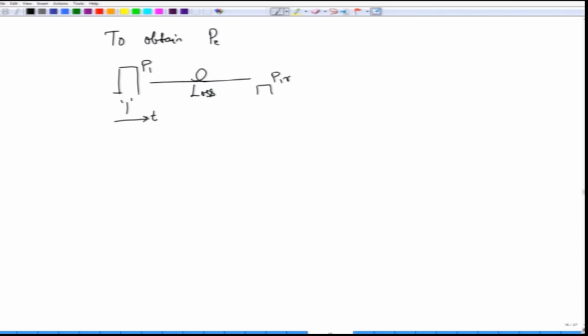So, here you have a pulse which is varying with respect to time, and let us assume that for all practical purposes the same pulse variation is maintained, except that the amplitude has now decreased. Again, this is varying with respect to time. If I put in a photodetector here, what am I going to generate at the output? I will be generating a current waveform, which looks very similar to the received optical waveform, multiplied by the responsivity of the photodetector. So, the current waveform that you are generating, which will again be a function of time, will be R times P1R.